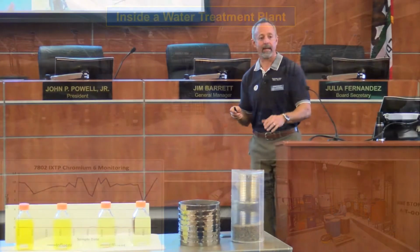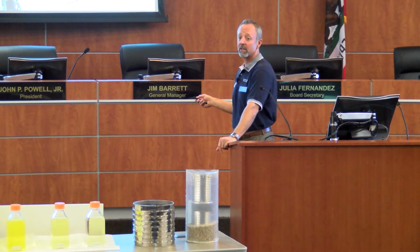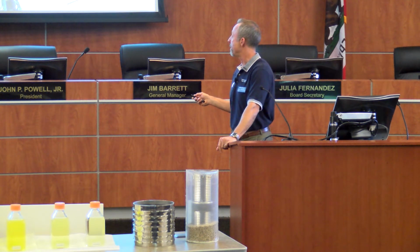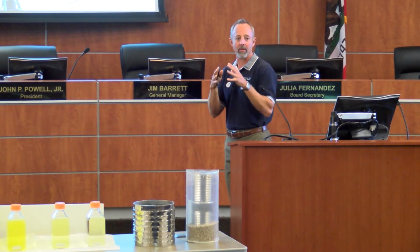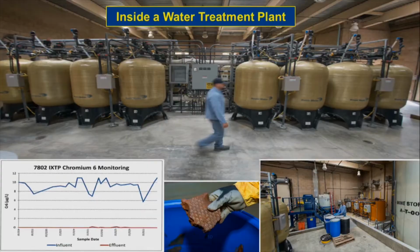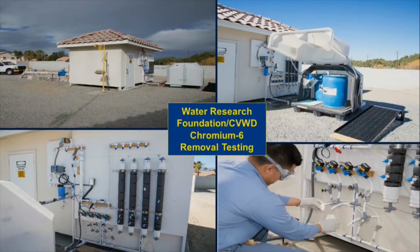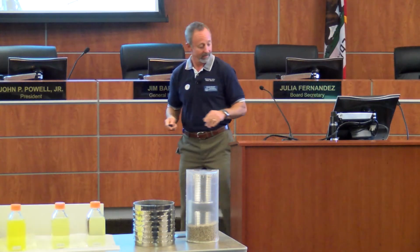So we concentrate the arsenic and the chromium and other ions into what looks like rust. And this is primarily iron. The iron absorbs to the arsenic and the chromium and you end up with this sludge. This has to go off to a special waste facility. And then the clean salt water can be put in a truck and driven to the ocean and put in the ocean. So it's a very expensive process. This triples the cost to deliver that water at this plant.